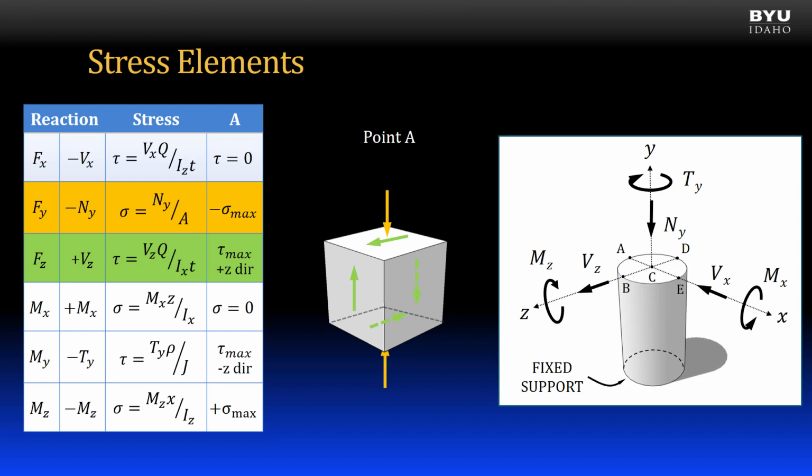Additional stresses must also be present on the z-axis front and back surfaces for equilibrium. When shear stresses are present, they will always show up on four sides of the element. Note that the arrowheads on adjacent pairs of shear stresses point towards the same corner. Next is the moment about the x-axis. It causes no normal stress on the element.